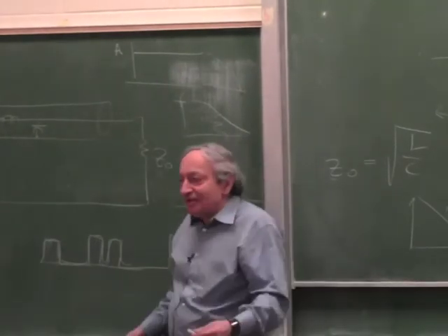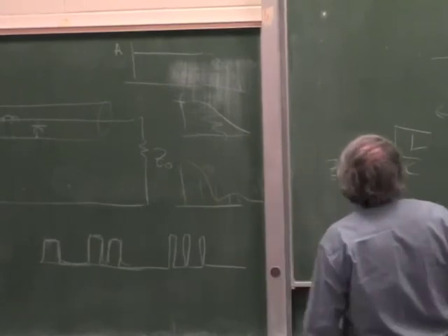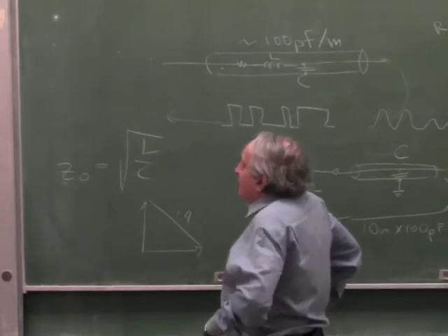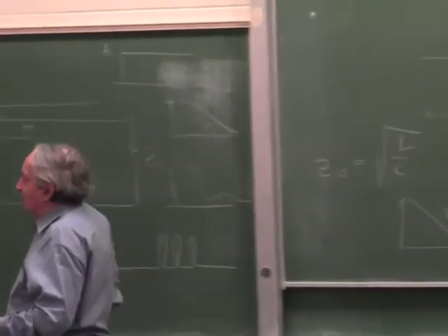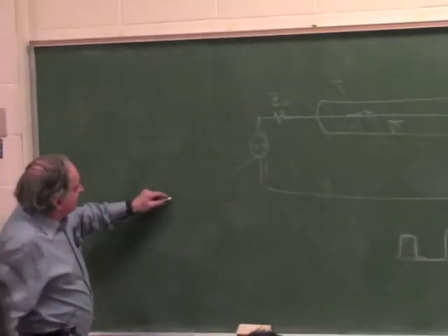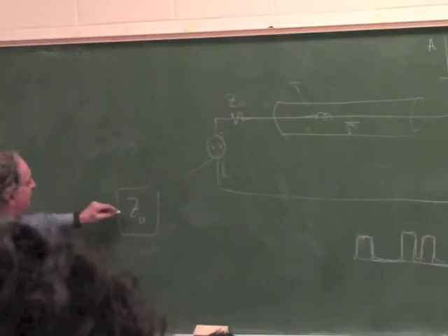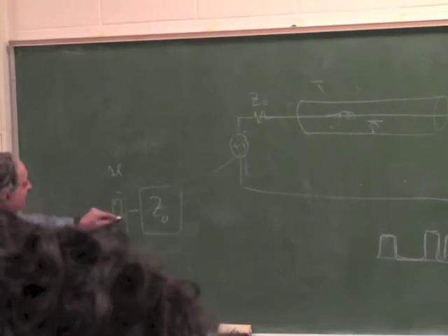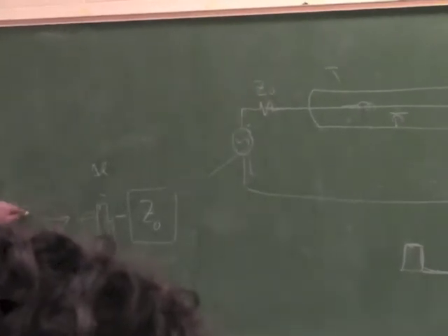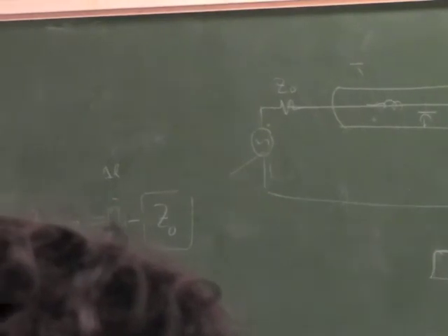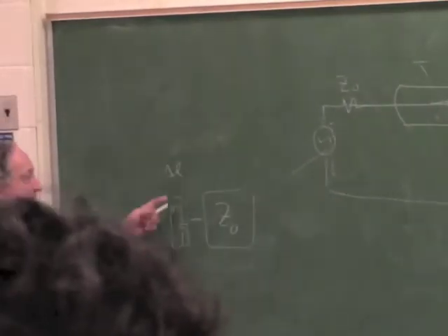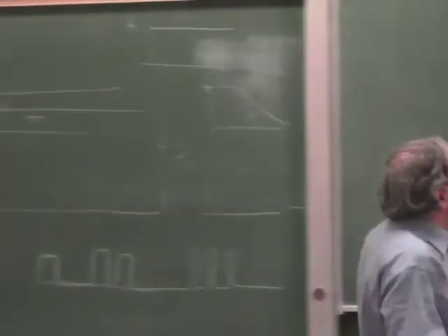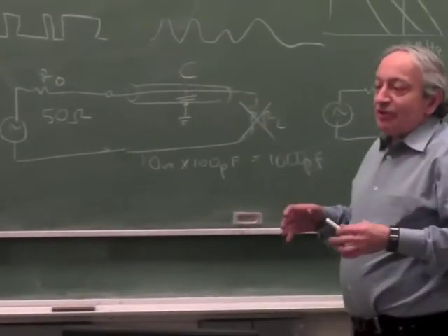Okay? And because of lack of time, I didn't prove to you that Z0 equals this, but if you want to prove it to yourself, you do what Heaviside did, as I reminded you. If you have a transmission line which has a Z0, and you add a little section, delta C and delta L, when you look inside, it should still be Z0. Then you write the equation, make delta L go to 0, and you get this. So if you're really curious, you can convince yourself with that. So, whenever you put a piece of cable,